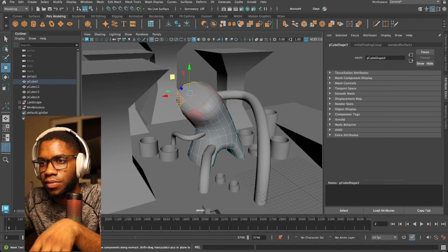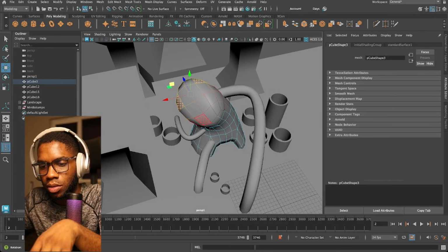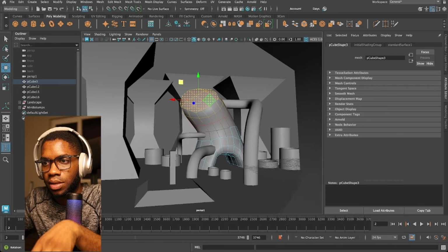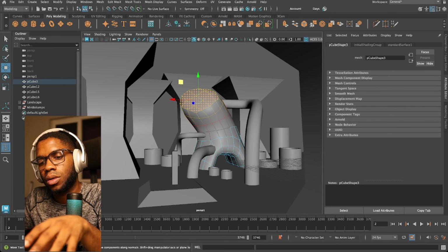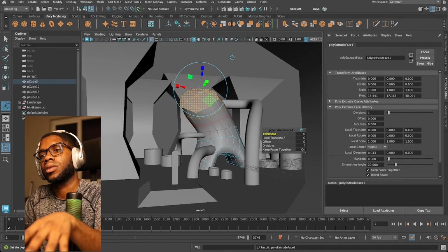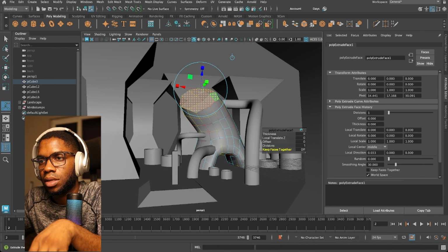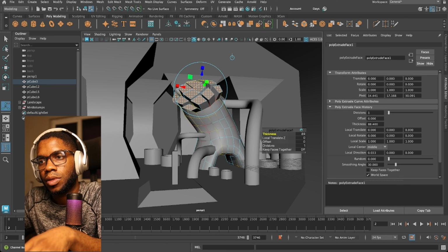Let's take out all of them. So you go bam. You can hold tab, that gives you like a paint selection, just like that. You get to select everything. So now when we do Control E for extrude, we're gonna select this option here, keep faces together, turn that off. And now when we increase the thickness, it comes out like that.